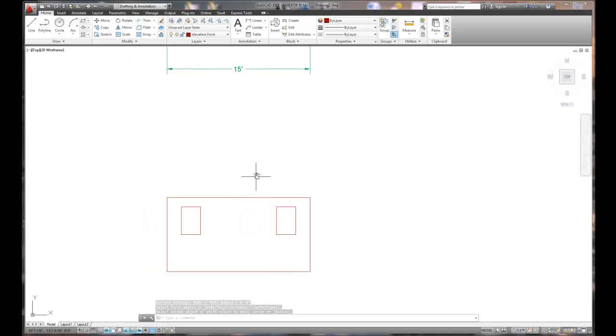Okay, so now the big question is, what's the pitch of the roof? Because that's what's going to calculate out how tall our roof will actually be. So let's make this cabin a 6/12 pitch. So for every lineal foot, it's going to move up 6 inches, and it's a pretty steep roof. So this would be good for snow country or additional storage or a loft area inside the ceiling. So for every 1 foot linear, we go up 6 inches. So basically the calculation is 15 feet divided by 2, or 7.5 feet. So in the center, it should be 7.5 feet tall.